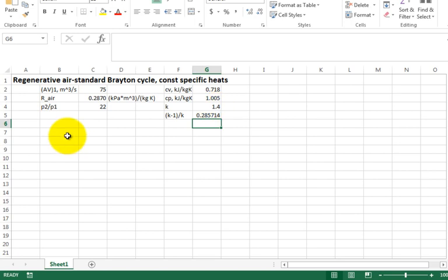Now, I'll make a table of my different states. Maybe I'll put state here, and then I'll have 1. Then I'll go to the compressor. If it would have just been the compressor, isentropic compression, no efficiency given, I would just say state 2. But now I've got to do it in analysis steps. I'll have to go to 2S and then 2 actual because of that isentropic efficiency.